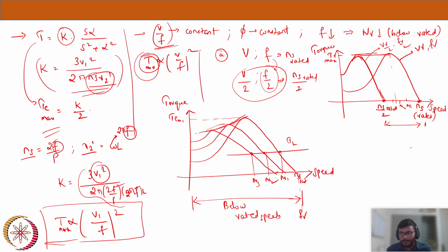So it's just a simple logic, right? The answer is yes, of course we can. As we keep on reducing the frequency from 50, we came down to 30, 25, 20, and so on. Now just increase the frequency, go from 50 to 55, 60, 65. You increase it, you can get a speed control above rated speeds, right?